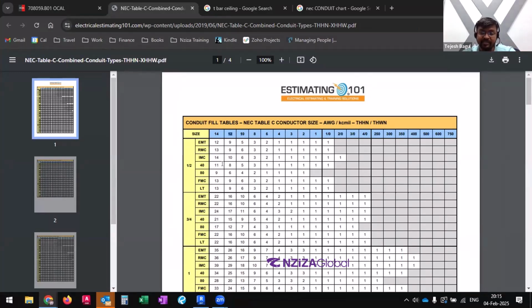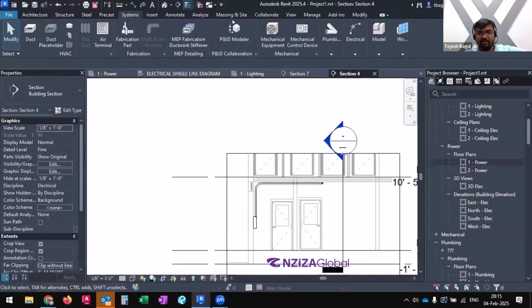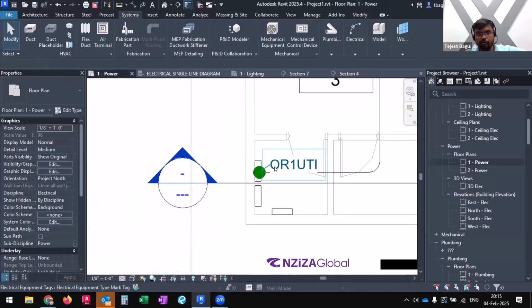And since it is interior, you can also have the 1/2 inch that will be going through it. So 1/2 inch for 40 scheduled PVC, since it's interior, you can go a maximum of 5 wires. So that will include your phase and neutral, and if required, the given ground as well. So that is how you will do it, similar to what we are talking about piping that we had seen on Friday. But that is how you can get the conduit routed.